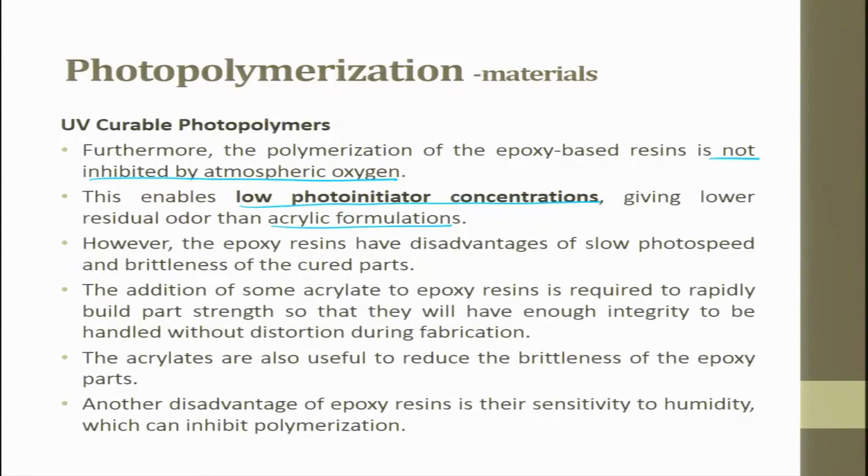However, the epoxy resins have disadvantages of slow photo speeds and brittleness of the cured part because it is thermoset. The addition of some acrylate to epoxy resin is required to rapidly build part strength so that they will have enough integrity to be handled without distorting during fabrication.